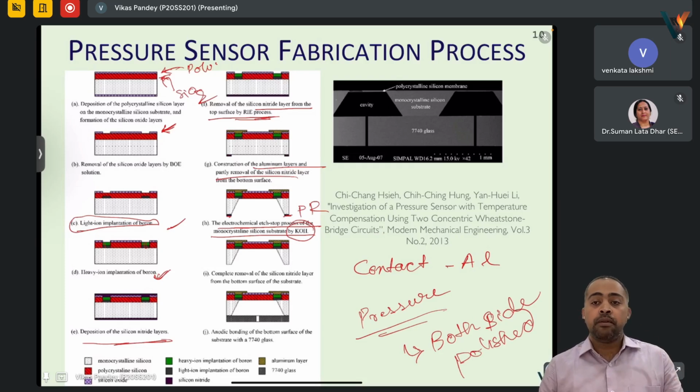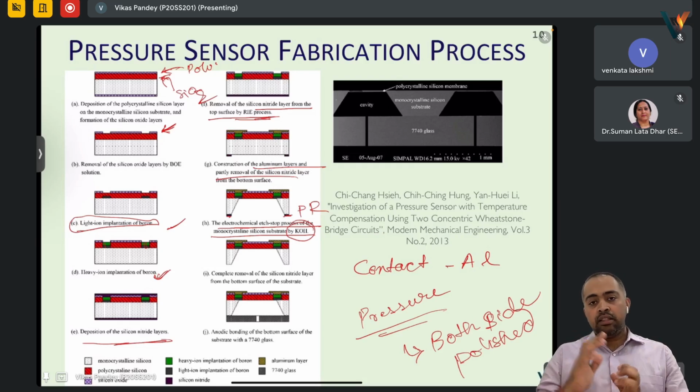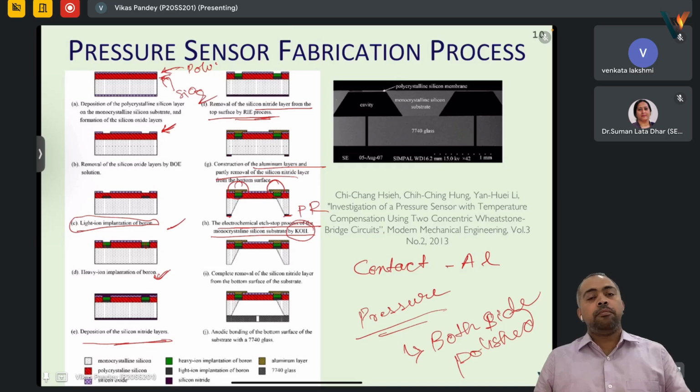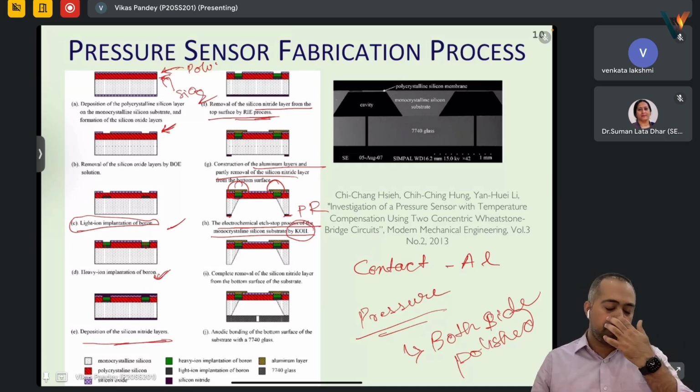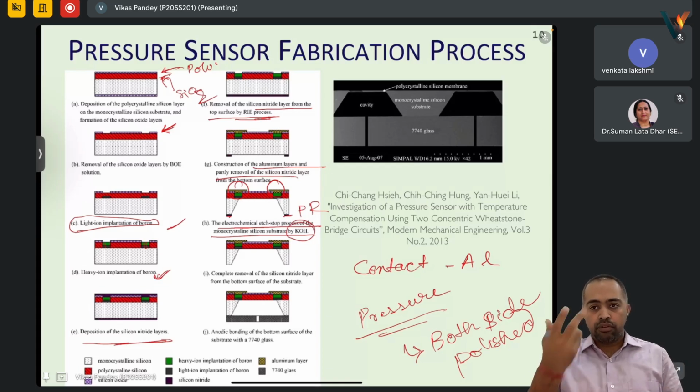As well, when you are doing the lithography on the back, it must be aligned in such a way that it is falling exactly at the positions where we defined the resistances earlier. To do this, there is a bit of advancement needed for MEMS lithography: there are cameras on the bottom of the wafer.